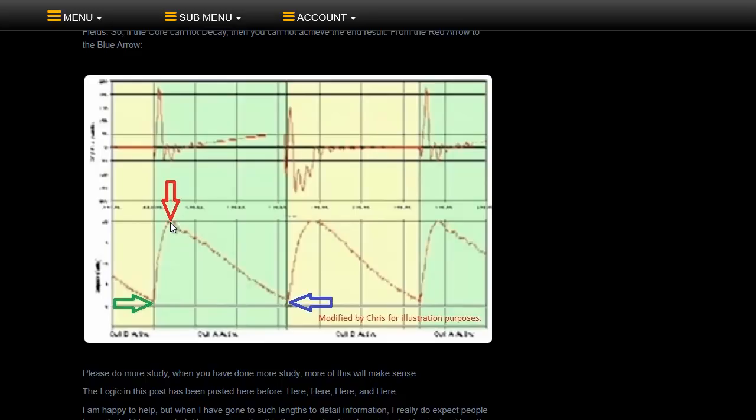Okay, so remembering again what we talked about, magnetic fields pump all the way up to the top. So these are 2 magnetic fields opposing each other on the output coils. The input coil is assisted by 1 output coil, and then opposed by the other output coil. Okay, so we have a reduced impedance effect all the way up to here. So we can get a very, very fast increase in amplitude all the way to the top.